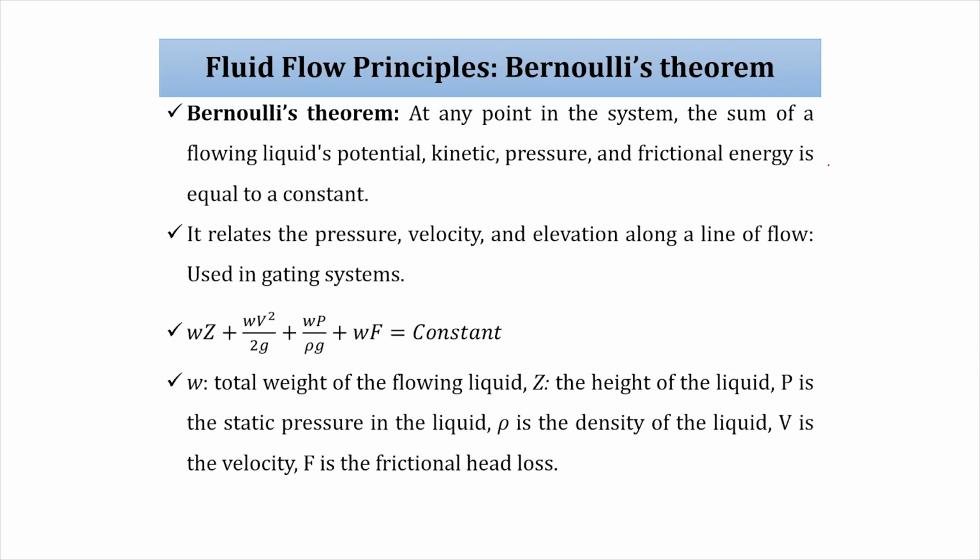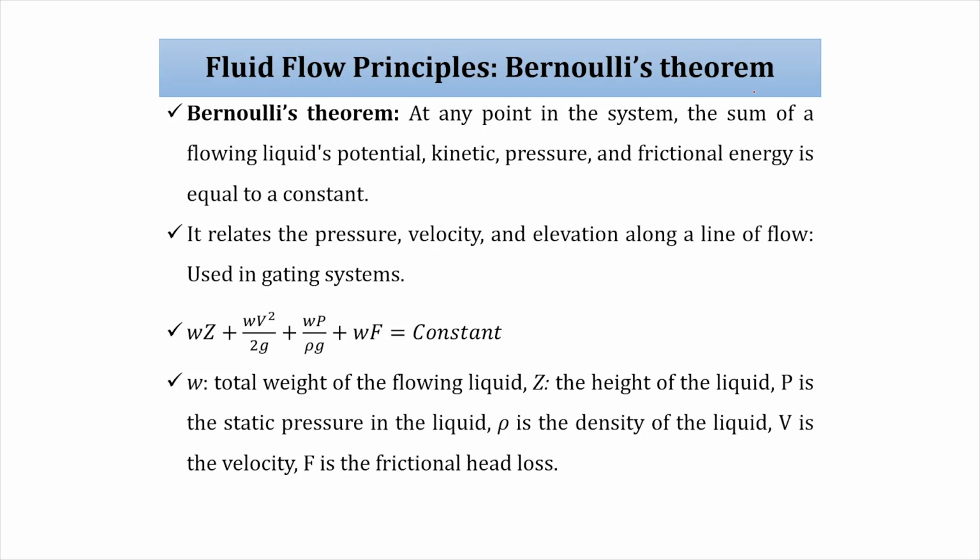So, in this flow phenomenon, mold filling, the molten metal is going to flow. There are three principles used to understand how mold cavity filling happens in the casting. First is the Bernoulli principle or Bernoulli theorem. Bernoulli theorem suggests that at any point in the system, the sum of the flowing liquid's potential energy, kinetic energy, pressure energy and frictional energy is equal and constant. The summation of these four energies at any point will be the same. Directly saying, energy is conserved.